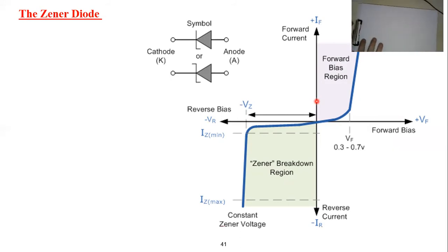What is the Zener diode? A Zener diode is some sort of electrical diode, which has a very interesting IV characteristic curve, but in the reverse direction, not in the forward. In the forward, it's just a normal diode with a voltage drop of 0.7 or 0.5 or whatever. However, it's very interesting in the reverse bias, because it can clip the voltage to what's called the VZ.